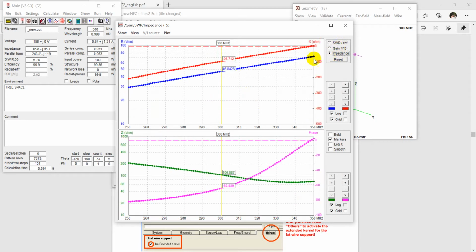So we need the impedance. When we take the impedance, you can see the value is increasing tremendously at the right side of the parameter. The optimum frequency of our desired frequency is 300 megahertz, but here is the resonance frequency.